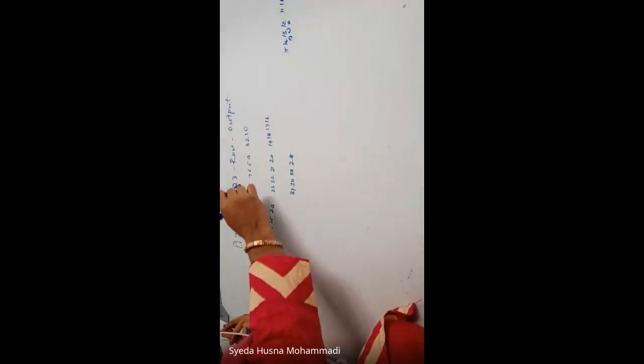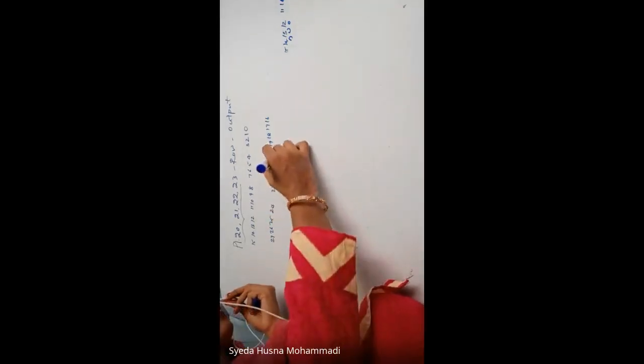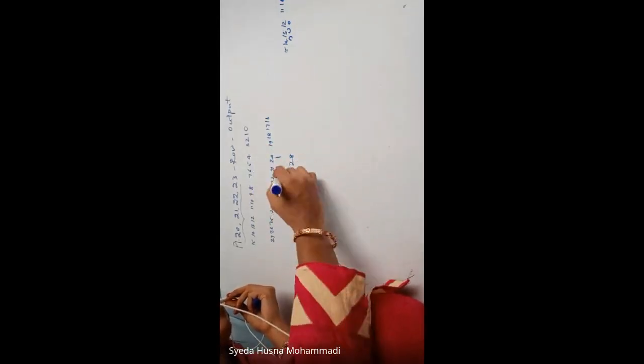Yes, ma'am. Okay, so now I have to set it in the direction of the output. If I have to set all the pins in the direction of the output, what should be the value on 20, 21, 22 and 23? Already I've taught you all these things. 1. Very good. The value on 20, 21, 22 and 23 should be 1.